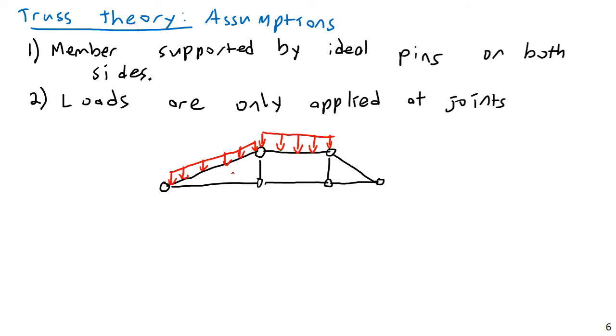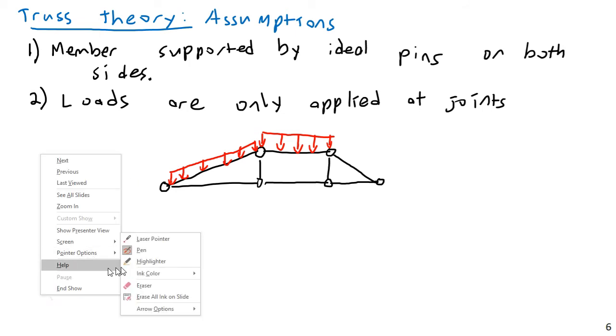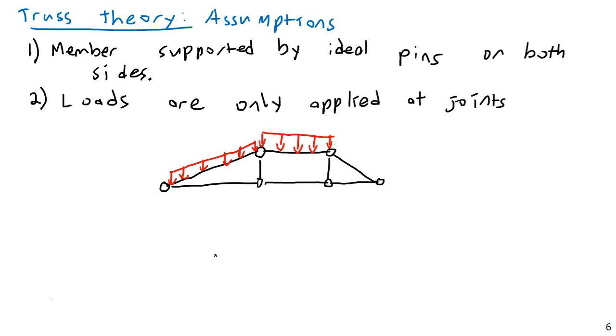Nowadays if you're designing bridges, you're going to use computer models and such, but if you were designing a bridge a long time ago using purely hand methods, the way you would do this is you would analyze the entire thing as a truss, but then you would design each individual truss member like a little beam. So you would make sure this member itself had enough bending capacity for its own self-weight or any loads that you apply to it, and then you would design the global loads, the global stability, based on a truss model.